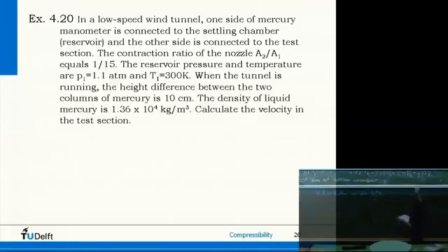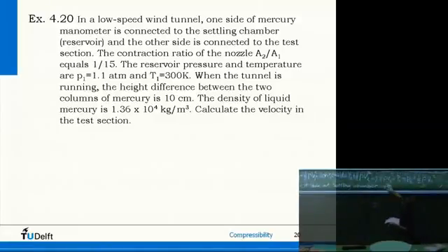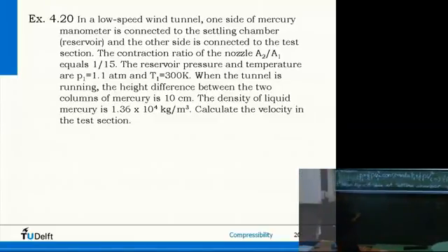Okay, so let's quickly do it. It's not so interesting anymore. So we have half rho V2 squared is equal to P1 minus P2 plus a half rho V1 squared. So that is equal to (A2 over A1) squared V2 squared.